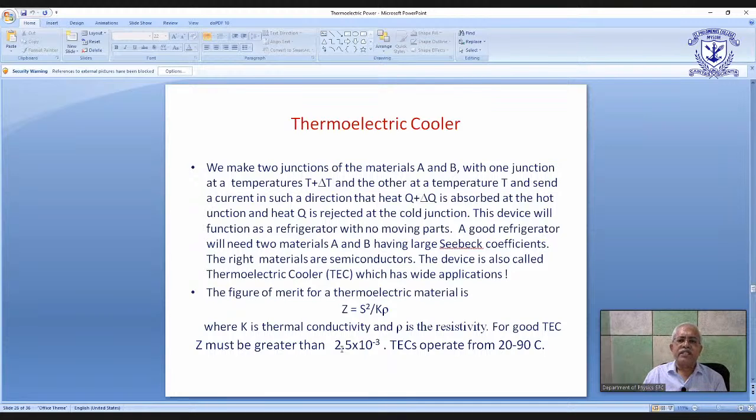On the other hand, the cold junction can be pasted on another block of highly conducting metal, and this block of metal will get cooler and cooler because the junction which is attached to it absorbs the heat from this metal piece. So you can have a platform which continuously gets cooled and another platform to which the heat is transferred and it emits the heat at that junction, which is thrown out into the outside atmosphere. So this will function like a refrigerator.